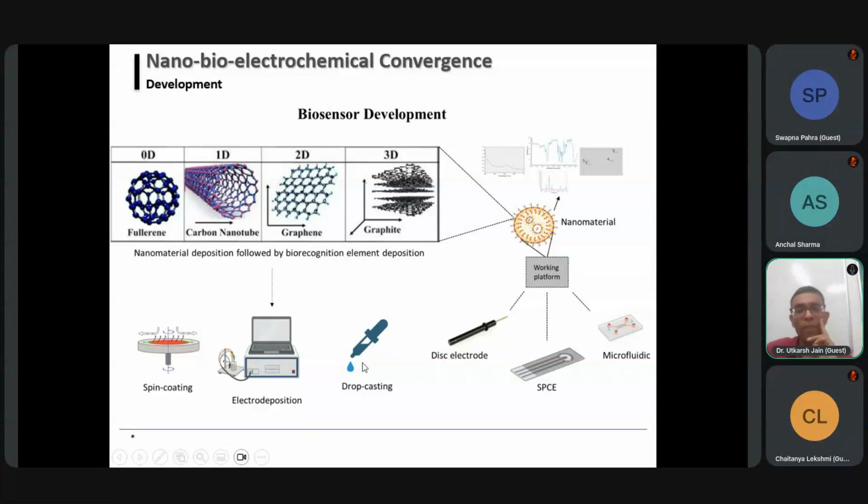If you are working on an enzyme-based biosensor, then you need to coat these enzymes on the working electrode, and sometimes you need to have the covalent linking, which is more effective. But to get the preliminary signals, you can screen through drop casting, where you load the proper drop of an enzyme on the working electrode, and then you can get the sample.